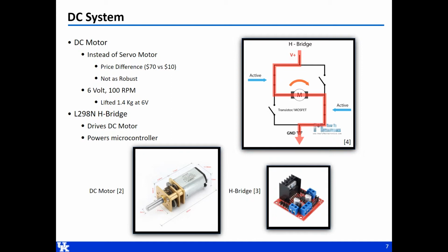We'll talk about that a little bit more later on in the slides, but as a quick explanation, the DC motor doesn't know what its position is, obviously, whereas a servo would know that and would be able to run through different commands, whereas the DC motor is a very sequential command input because it's time related.